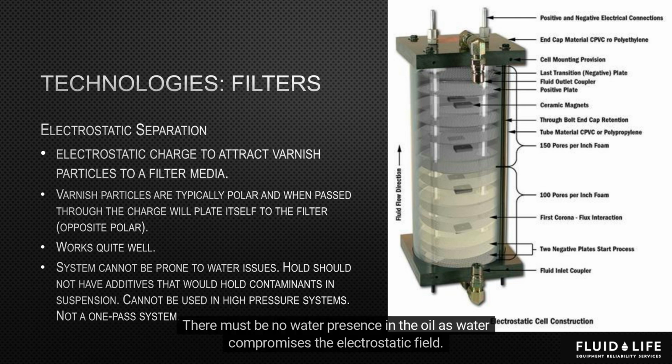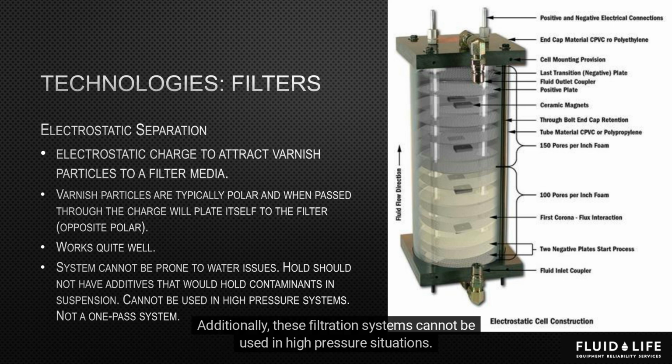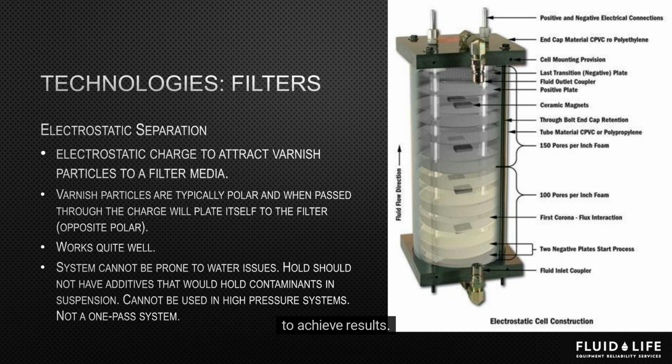There must be no water presence in the oil, as water compromises the electrostatic field. Another condition is that the oil does not contain detergent or dispersant additives that would hold contaminants in suspension. Additionally, these filtration systems cannot be used in high-pressure situations. Because the flow rate of these systems is quite low, they cannot filter a large volume of oil quickly. These are not one-pass systems and would need to be run continuously for an extended period of time to achieve results.